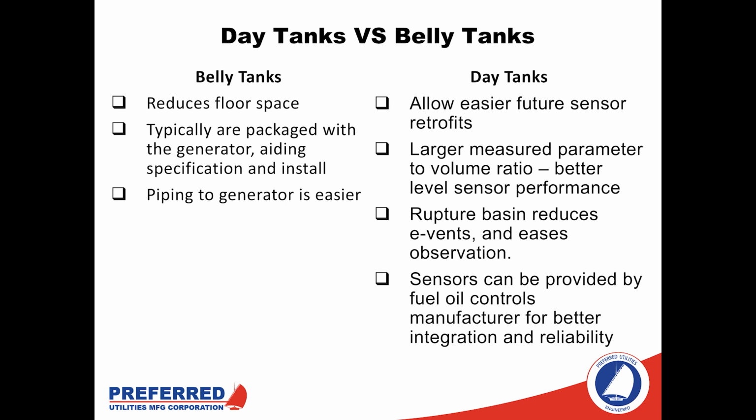Taking a look at another comparison, we have day tanks versus belly tanks. And if we think about those two pictures that we just saw, the belly tank being the one on the bottom and the day tank on the top. Now with day tanks, you're generally going to have more tappings, more standardized tappings that are going to allow better sensor retrofit, as we mentioned earlier. And it's also going to give you an advantage as far as measuring the fuel in it. So the entire system runs off the level sensor in that day tank, whether it's the transfer pumps or any of the alarms, high and low.